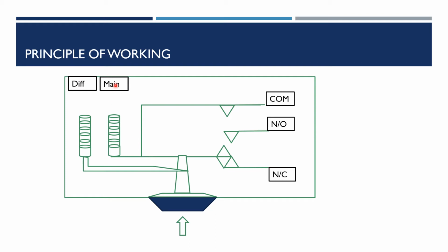We have two scales here. The first one is the main. This main scale, we're going to identify my upper limit, and I can change it with a screwdriver in the pressure switch. So whenever I want to raise it up, this